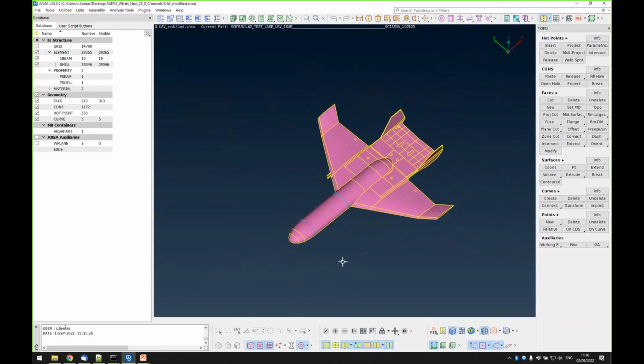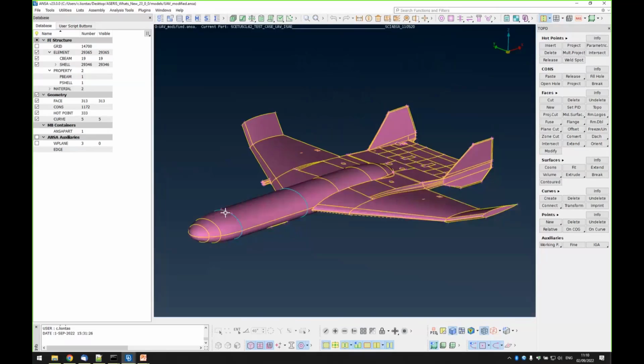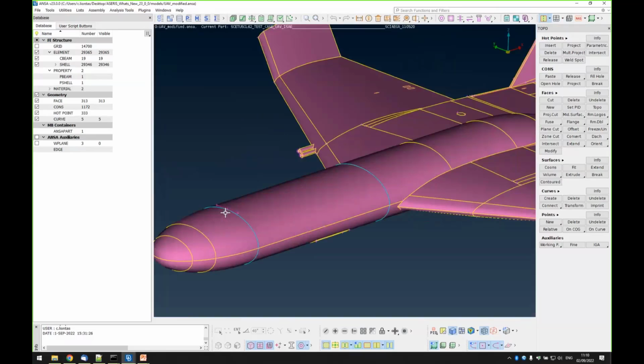And we also have a dipole antenna radiating closely to the top of the UAV. Let's say this is an antenna that is used by the UAV for communicating with other UAVs or ground stations. So here we have combined a radiation and a scattering problem. We want to see how this antenna radiates in the presence of the UAV, which is a problem called installed antenna performance. And we want also to see how the UAV is affected by external radiation. So we have a scattering problem.